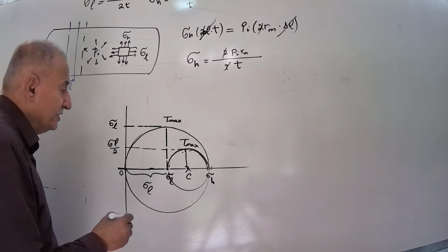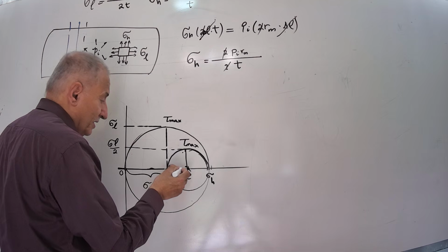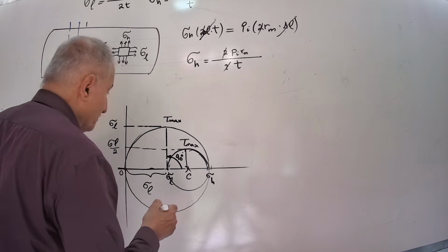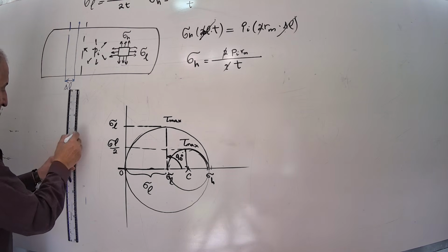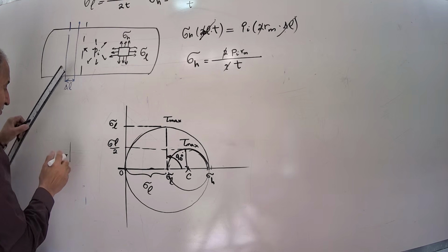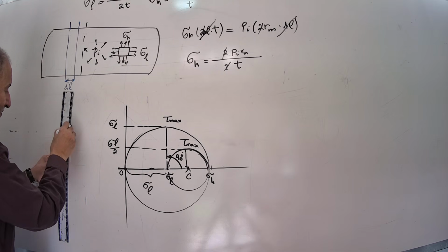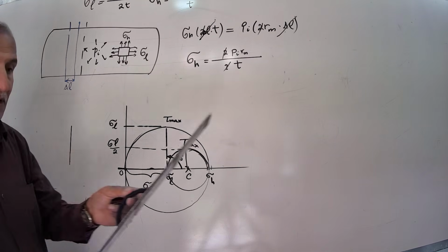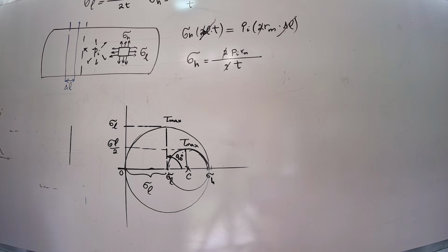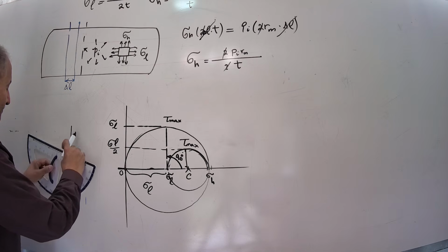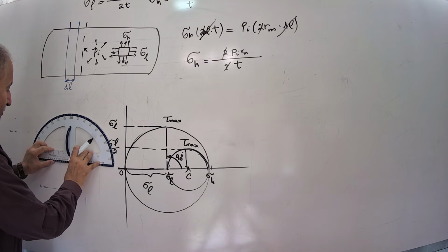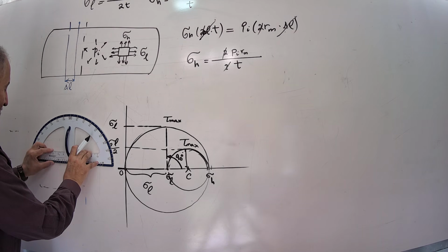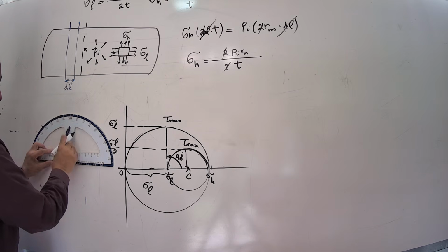What does it mean? It means if we rotate this element 90 degrees counterclockwise in the Mohr circle, which is 45 degrees in the element case, with this as the right side face, then we rotate it 45 degrees here.